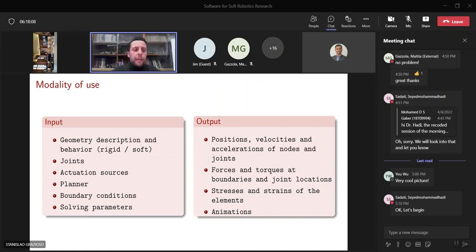We can include the joints, the lower pair joints that we have described, and the animation can be done both at joint level, so a classical joint motion, or we can have forces applied at certain nodes on our system to generate the simulation.